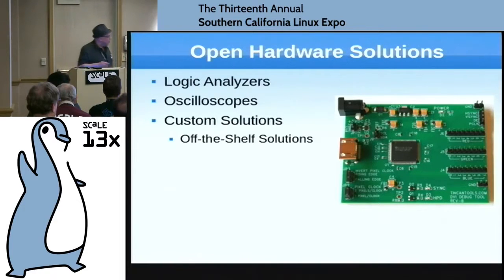We've actually got on the board itself debug headers here where I can hook these up to a logic analyzer for the red, green, and blue. We have the horizontal sync, vertical sync, data enable, and your pixel clock. And we actually also have an EEPROM. Where's that one on here? Right here, that actually pretends to be the EDID for a particular display. So you can actually pretend to be an LCD panel so that you can go through and debug it.